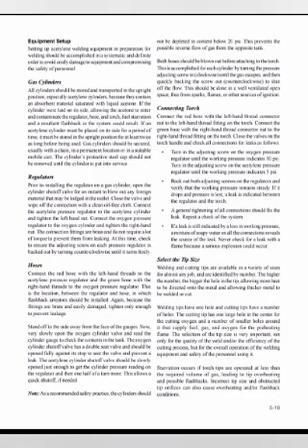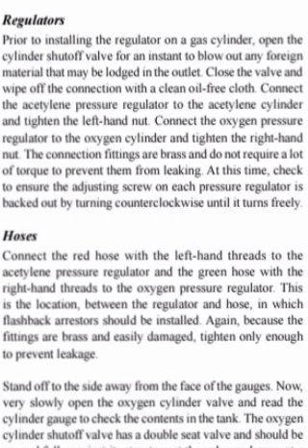Regulators. Prior to installing the regulator on a gas cylinder, open the cylinder shutoff valve for an instant to blow out any foreign material that may be lodged in the outlet. Close the valve and wipe off the connection with a clean, oil-free cloth.